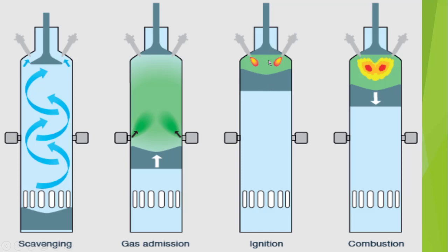It injects, and as the temperature of the surroundings is enough for the diesel to ignite, it acts as a primary combustion fuel, and therefore increases the overall temperature sufficiently for the auto ignition of the gas mixture.